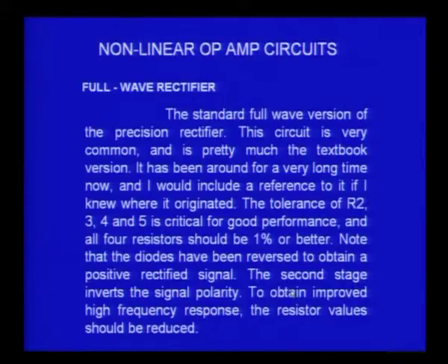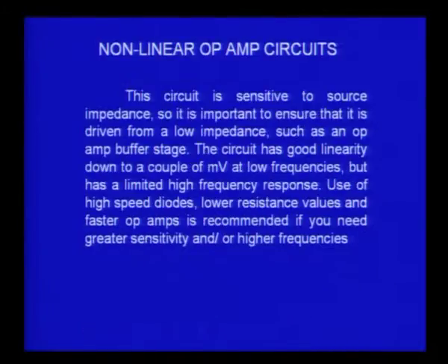We have to also worry about the high frequency response. The high frequency response of this circuit is not good when you use very large resistors. So, if you want to improve the high frequency response, you have to reduce the resistors that you make use of in the circuit, and also you should try to use a low impedance output from a signal source, the sinusoidal source.